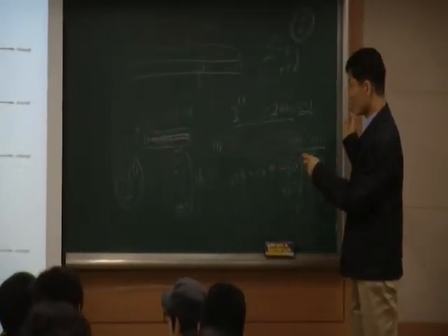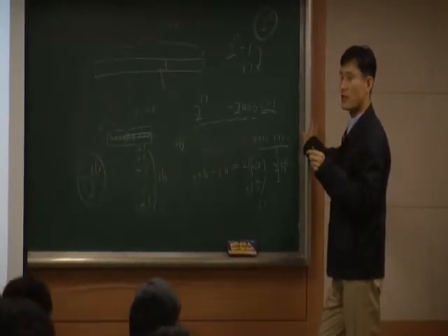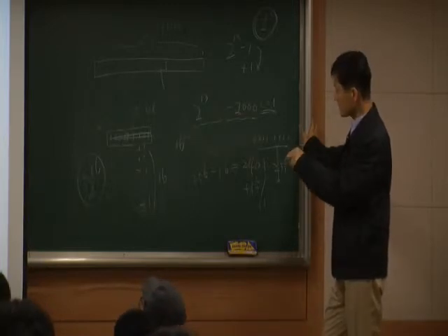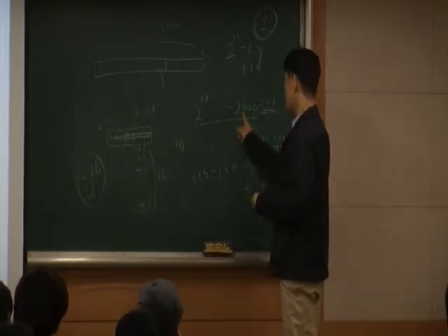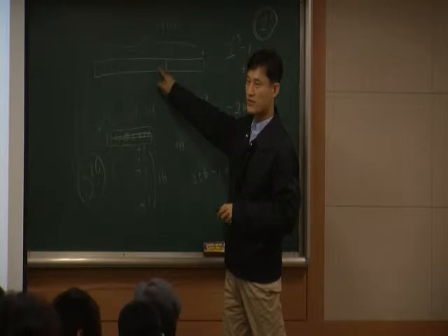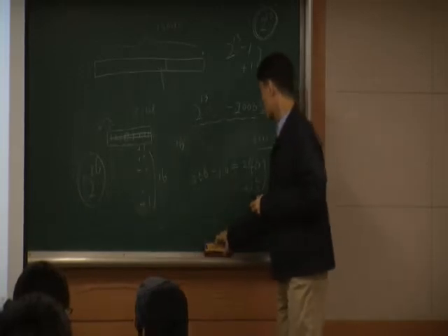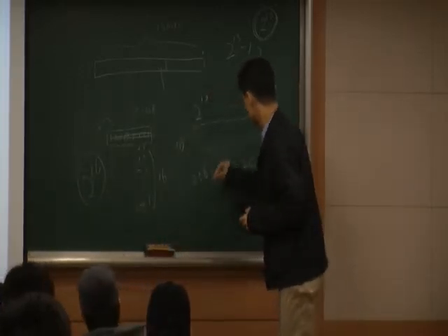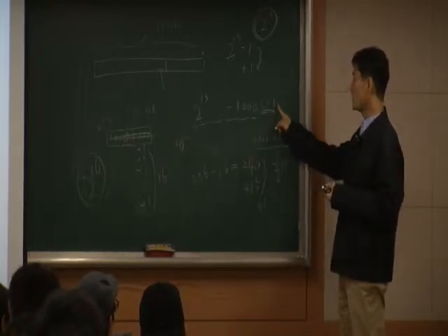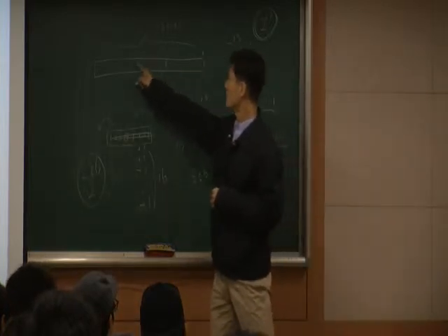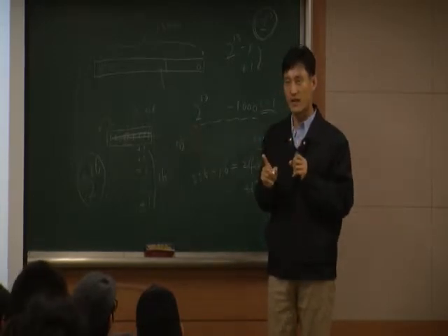In that case, what you need to do here is that in order to measure 1 millisecond delay, this is going to be the initial value you have, right? So let's write this value here as an initial value and run the timer. Okay, and then you get the 1,000. Let's say this is 1,000. Then you get 1,000 pulses. After 1,000 pulses, that's exactly 1 millisecond. Now we have a carry on, and this value now becomes all 0. And that's exactly when you have a 1 millisecond delay.